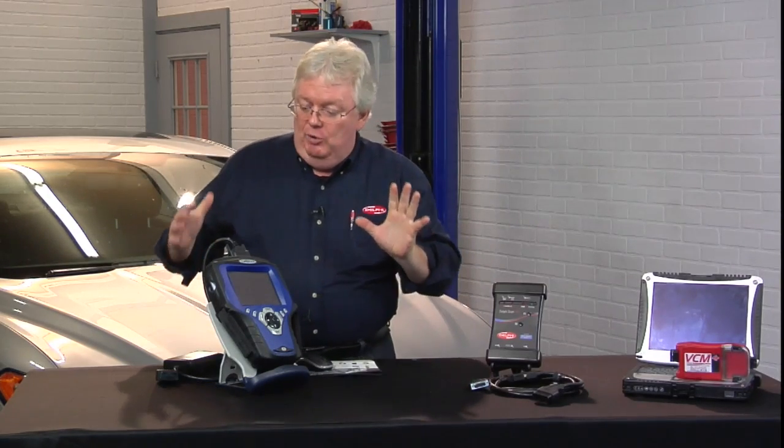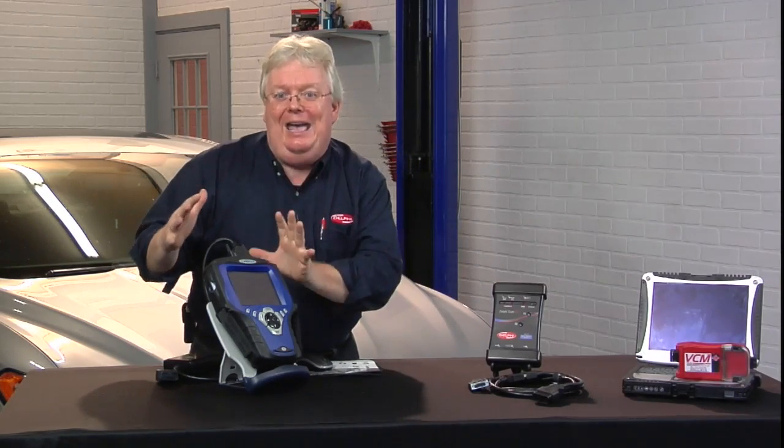So it's always good to go into global. Mode 6, I prefer enhanced powertrain. But on other things, I go to global a lot. On CAN bus vehicles, you're seeing dozens of PIDs instead of a handful of PIDs in global. And the PIDs will be the real McCoy numbers, not the fail-soft made-up default numbers.